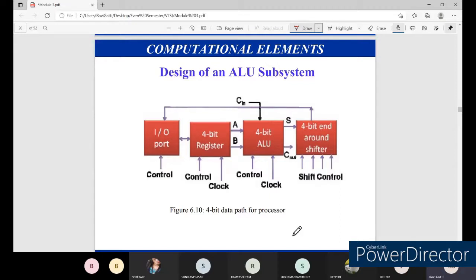You can see here, the output of this 4-bit adder is given to the shifters. Based upon the shifters, we can take that output and perform operations depending upon what it has to undergo next. The output of this 4-bit adder gives one sum and one carry, and this carry we will be shifting to the 4-bit parallel sum of the ALU.